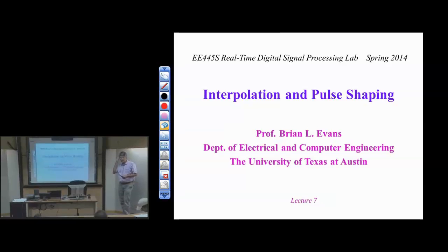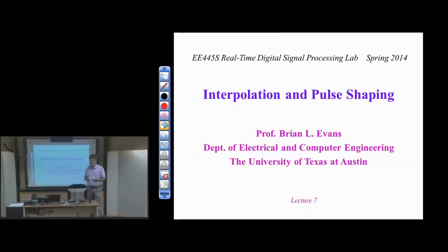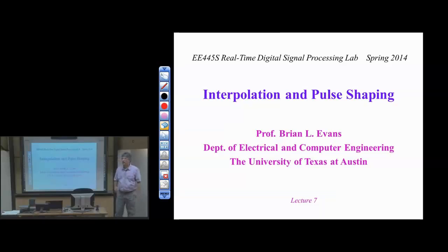But there's a trade-off, right? The more oversampling we do, the more complexity we have to have in our system. We have to process the samples faster, need a faster processor. Filter orders go up typically as we increase the oversampling rate to meet the same magnitude specs, and now we need more buffering, and we also now have more multiply accumulates per sample and more samples per second. So there's a trade-off point where you say enough oversampling, maybe it's 4x, 10x, 500x, depends on the application.